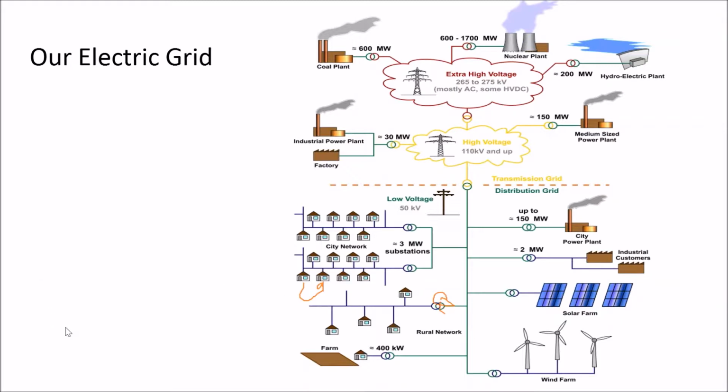But what happens when all of your neighbors on your block get solar is all of a sudden you're backfeeding this distribution transformer. And if that transformer is not capable of bidirectional metering, when it's being backfed, what it registers is that there's a grid fault. It might be that a tree has fallen over some distribution power lines. So automatically, the electric grid needs to shut off because we don't want high voltage power arcing into first responders and making power lines deadly and unfixable. And so these distribution transformers turn off as soon as they're being backfed. The question is, who pays for upgrading that distribution transformer to bidirectional metering? The utility wants the solar customers to pay for it.